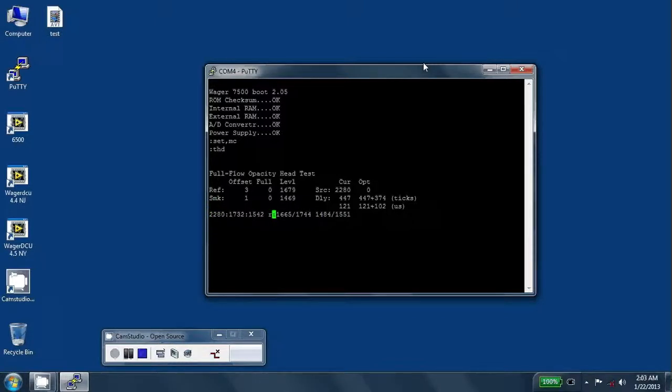At this point we want to make the adjustments of going ahead and turn up the digital values for the optics, and those points are located inside the optic tube on this physical circuit board potentiometer. Let's go ahead and start on the transmitter side first, and we'll inspect what the side the green light is, and that'll be the transmitter side, and we will go ahead and adjust the potentiometer clockwise to increase the value and counterclockwise to decrease the value.